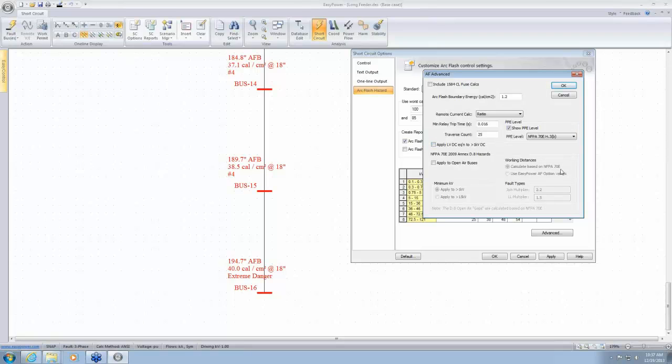And that one has been suggested for low voltage systems. So far there are no known published equations for medium or high voltage DC systems. And what we have done is allowed you to extend that equation to systems with voltages greater than 1 kV.